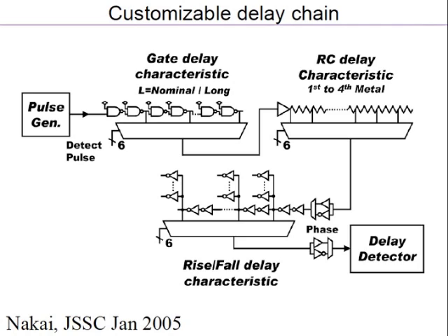So the question is, how is this testing done? That is something which we'll cover later in the course. There is a built-in self-test. You have to put extra infrastructure in the chip to allow you to do this testing. You'll also have testers, which are big, very expensive machines, in which you put the chip and the testing is done. So there is some help from within the chip, and it works together with the tester to actually finish the testing. The tester time is very expensive, so you want to do your testing in as little time as possible, so that the chip can quickly come out and you can say, is it good or is it bad?